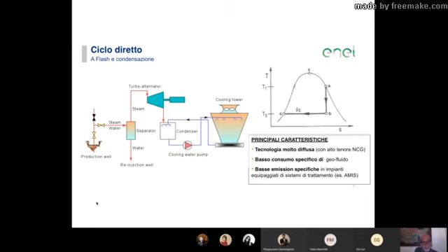Usually, for the deep geothermal system, you have original hydrostatic pressure of about 300 bars and about 300 centigrades temperature. You reduce the pressure to about 20-50 bars, and so you start to boil off the geothermal system. And this is relatively good and efficient simply because by boiling off and producing vapor directly into your geothermal system,